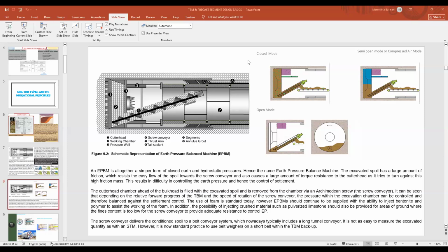Okay. One more question, sir. When you are using a hydroshield in slurry TBM, when we are encountering water, in that situation we use a hydroshield. Yes, if it is a very high water ingress, then you have to use a hydroshield. If you are working in Calcutta, you cannot expect anything else, it's always closed mode. And in Bowbazar also, where ITD was working, at that time the water pressure was so high that it entered the machine through the tail end, because the pressure was so high.